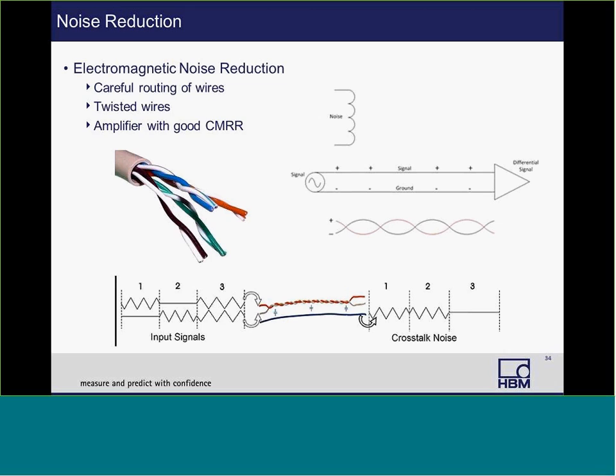If you lay your strain gauges such that there is a longer distance to, say, half the bridge versus the other half of the bridge, you should still use the same length wires. But don't coil them.